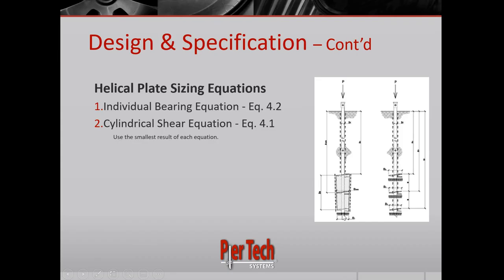So those are the two different ways that the pile capacity can be calculated, and the helical pile design engineer will run those calculations for both equations and take the lowest value of each one. For those of you that want to understand this a little better, go to starting around page 24 of our engineering manual. You can read all about these equations and learn more about how these loads transfer in the pile.